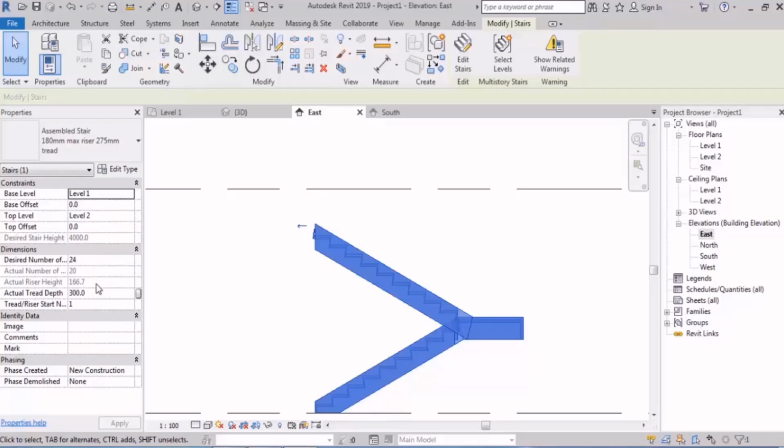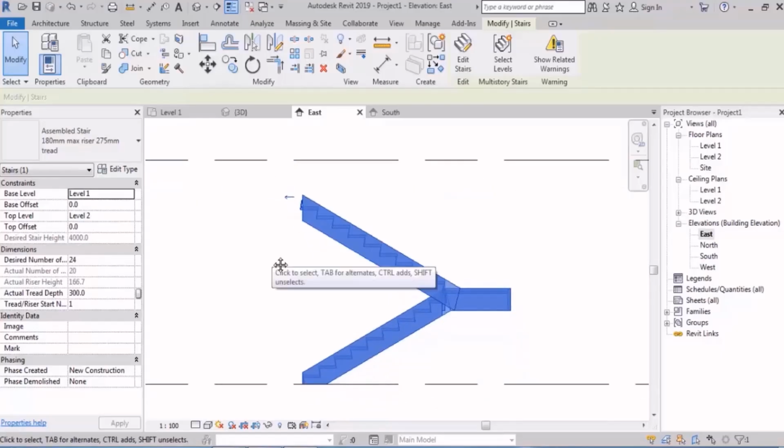Well, when I edit my stair here, for example, I change the direction of this a little and then trim these two. When I click on finish, what error does it show us? Invalid stair path. That's right. Because this line has not reached that line under it. Alright, I told you it must be connected to the first and the last riser. So I select it and then correct it and finish. Alright, now we nearly checked the errors of stair.